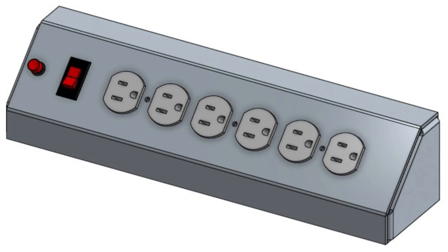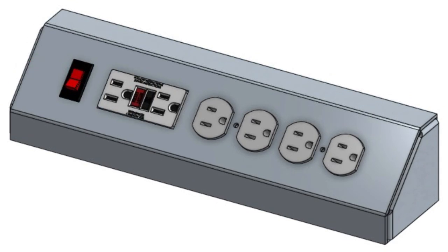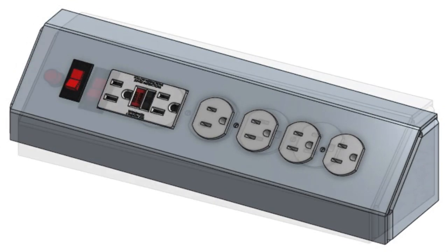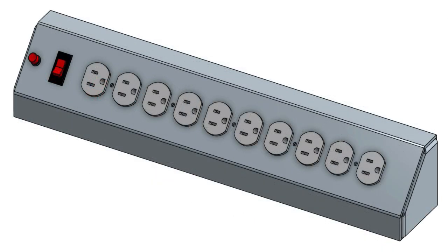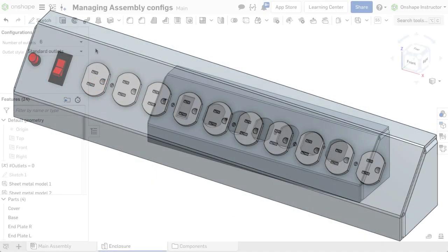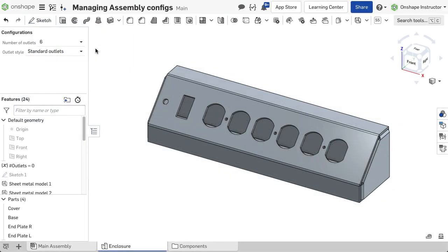When working with configurations, it is likely that updates are required in the future to accommodate design changes. This might include adding new components or adjusting mates. Make sure all referenced objects are updated as you intend when making these configuration changes.